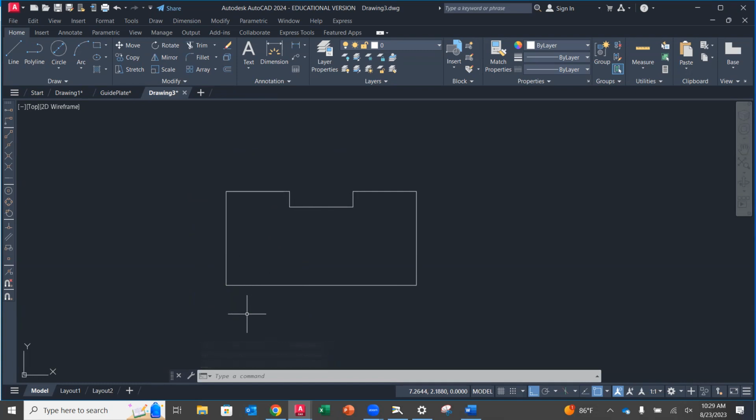How'd you guys do with that? It's called the dynamic input, where you can kind of move your cursor along and then give it its distance. Now, the important thing there was that I had ortho on so that I would have horizontal and vertical lines all the way through. Okay.